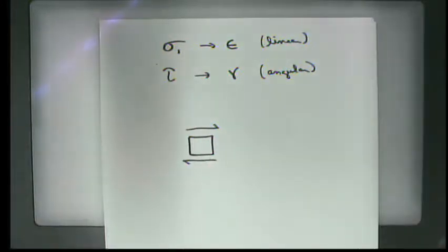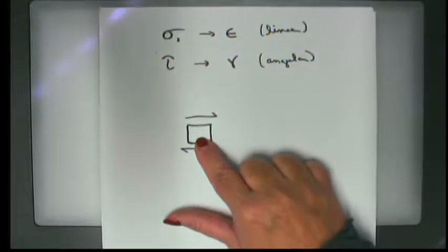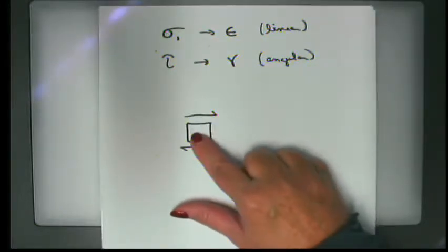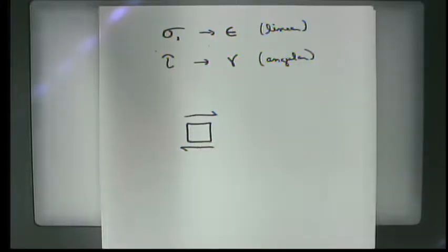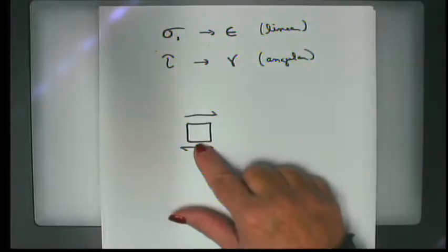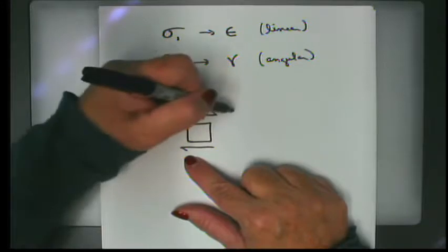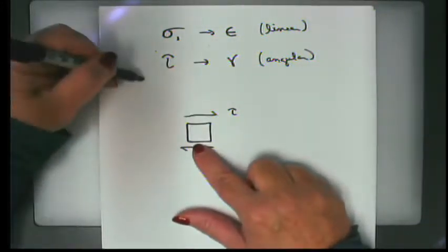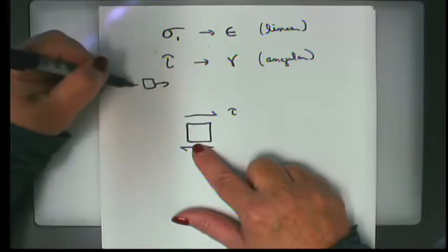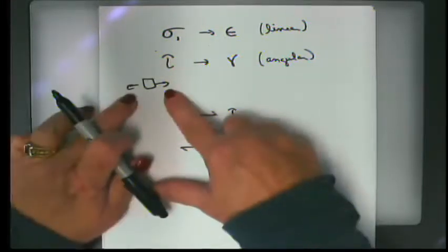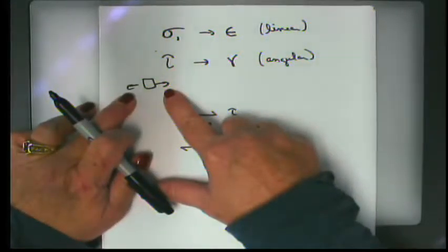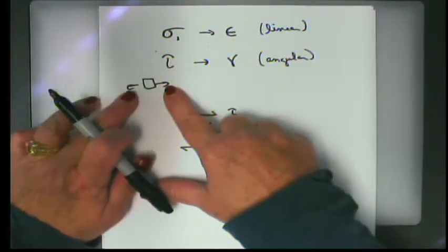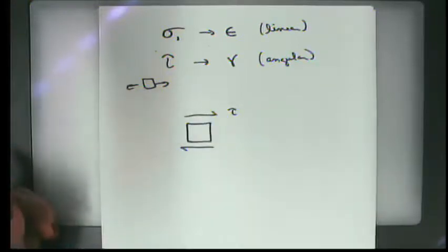And so if we look at this, this is a little analysis technique that we'll be using in the future. This is called a stress block. So we're just looking at a tiny little piece, a finite element of a structural member. And a shearing stress would exhibit itself this way, in that, remember when we had an axial load, it would look like this. Now, if you look at this particular type of an axial load and a sigma, you can see that one force directly opposes it and results in static equilibrium.